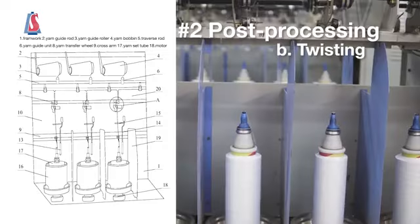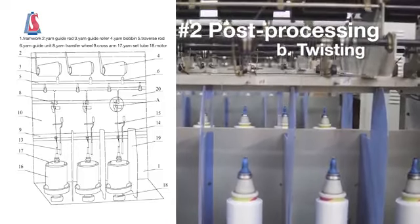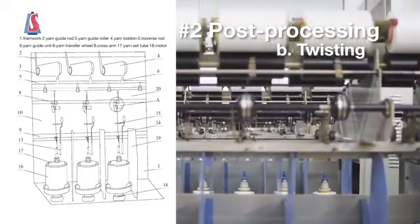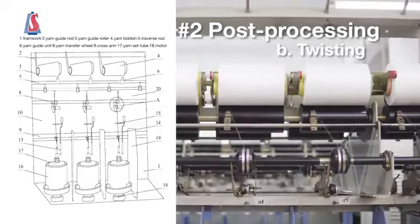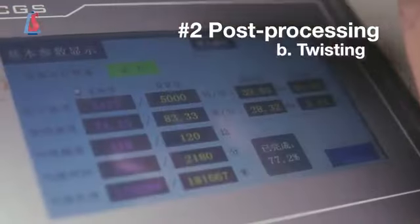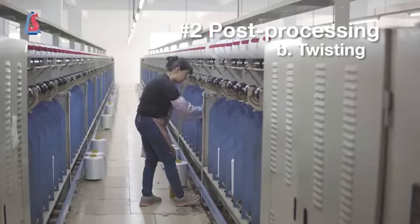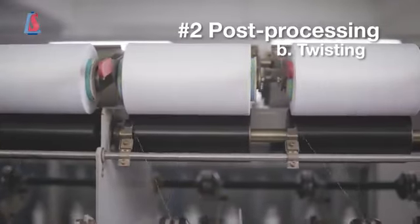Twisting. Twisting refers to combining 2 or several single yarns together and twisting them through a machine to produce strong elastic strands with the properties of uniform thickness, smooth surface, and wear resistance to meet the needs of the subsequent process. The workers will set the twist on the machine according to the customer's requirements and wind one end of the DTY on the machine, and the machine will operate the twisting process.